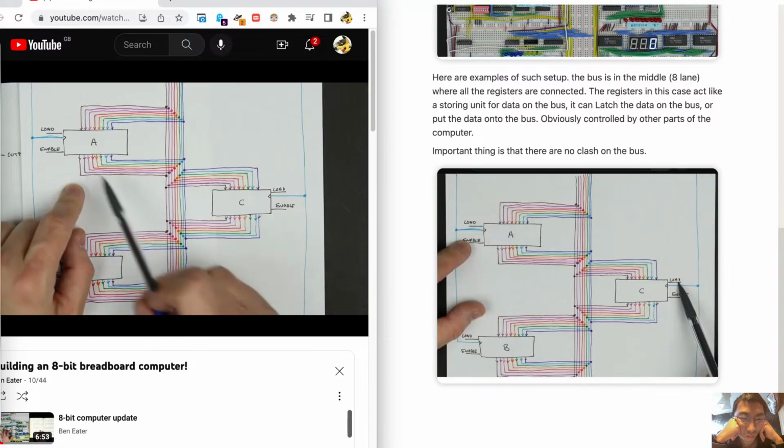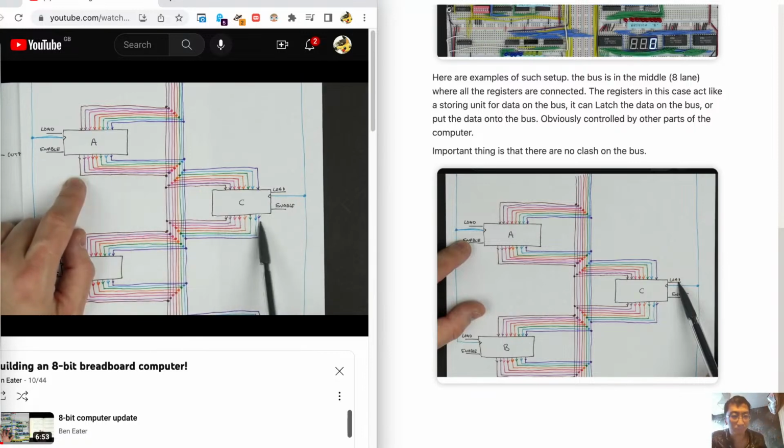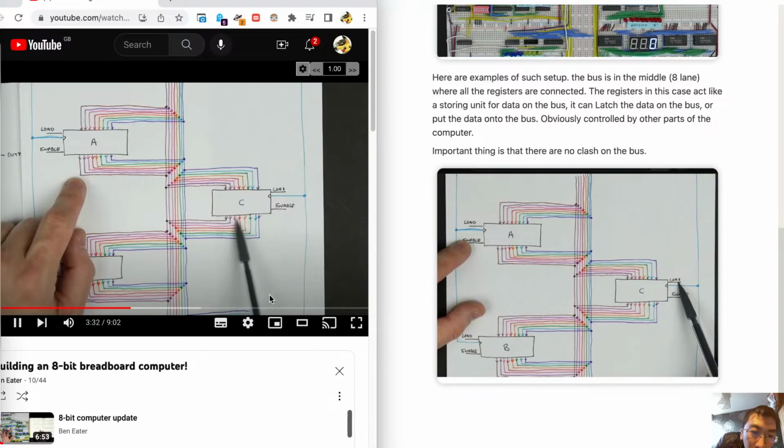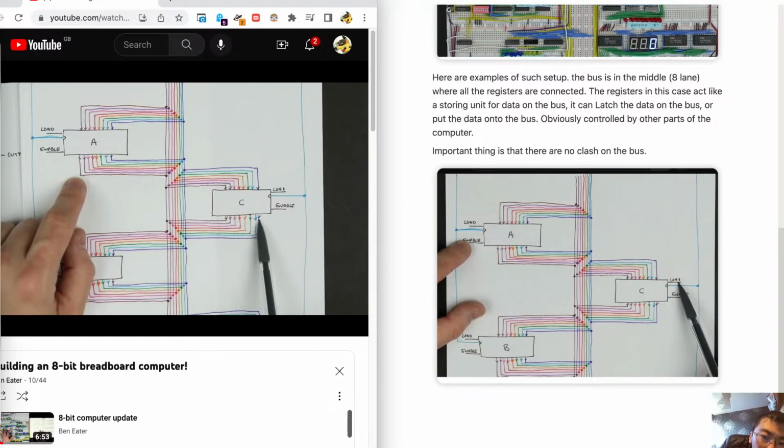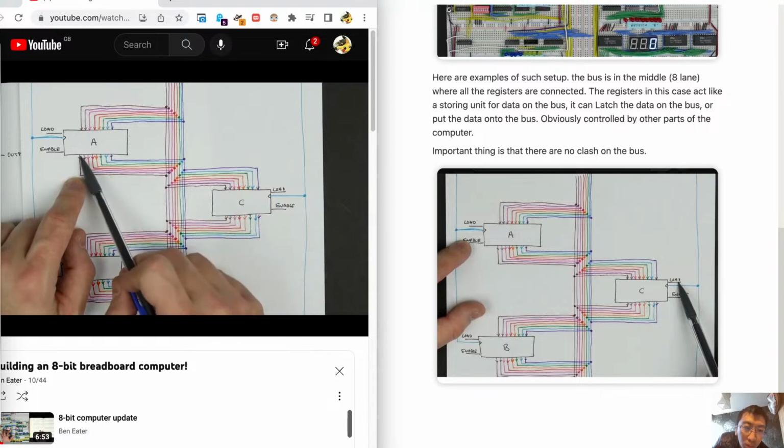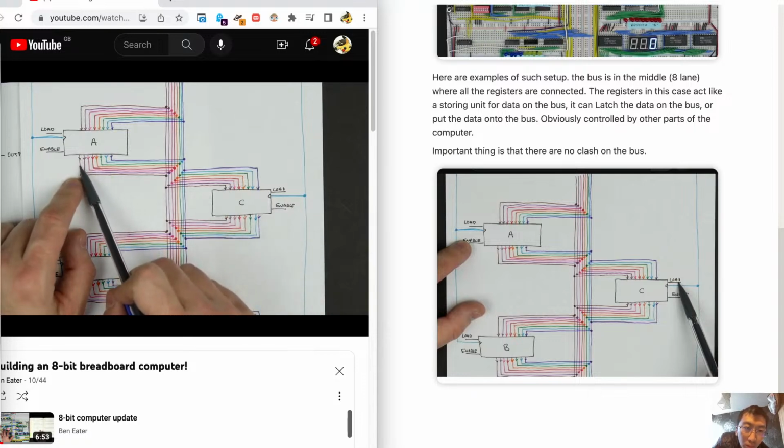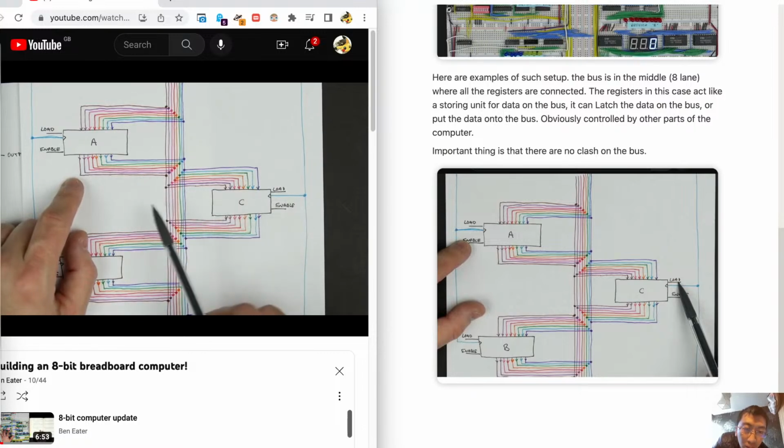So if for example you said, okay, well C is not going to output anything, so it'll set all these to 0. Well, that's no good, because what that means, if you're setting all of these to 0, is that it's going to sink current, and so if you have a 1 here, you're actually going to get current flowing out here and into the output here. That's not really what you want. You really want these to be essentially disconnected.